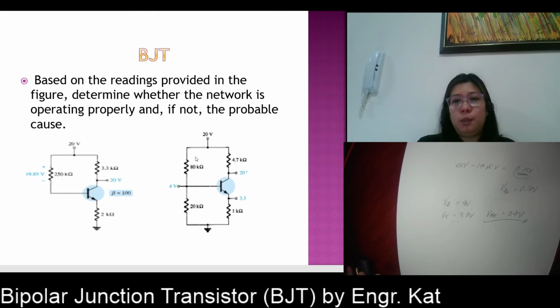Okay, so look at the specific value. And also look at this one, VCE. Okay, so that is how. We say that VBE must be equal to 0.7. So 0.7 was not properly observed here, while 0.7 was observed here. So here, the problem only lies at this point because this is functioning well.